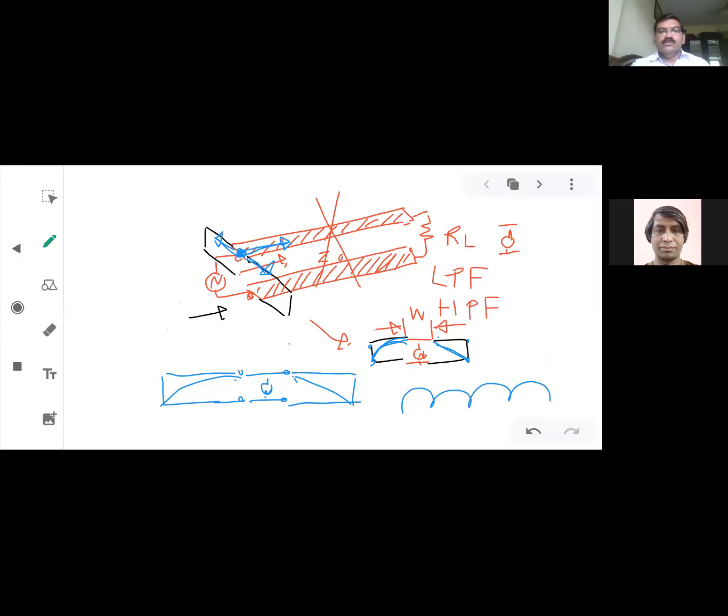Okay. Now we will see what happens if the frequency changes. See, the generator is operated at a certain frequency, and because of that frequency, you will get a certain lambda, and that lambda is such that the standing wave formed in the additional transmission line, this length, is exactly equal to lambda by 4, and here also this length is exactly equal to lambda by 4.